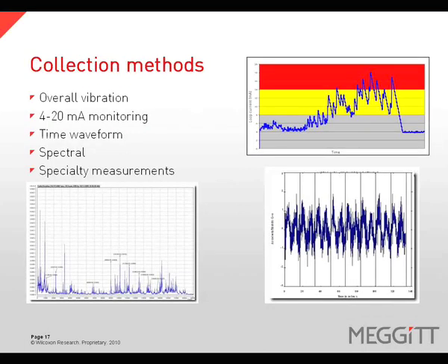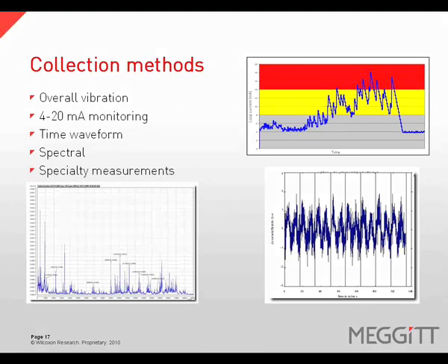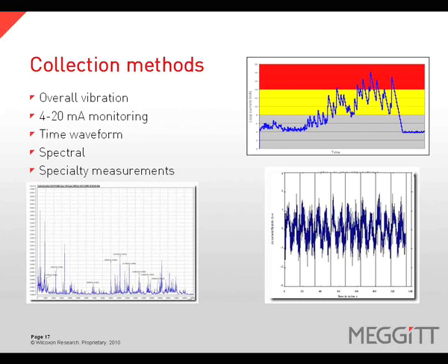There are several different types of vibration measurements. The most common are overall vibration, time waveform, spectrum or FFT, and specialty measurements such as peak view or enveloping. Each has its uses and often can complement each other when used together. We will discuss this in detail later.